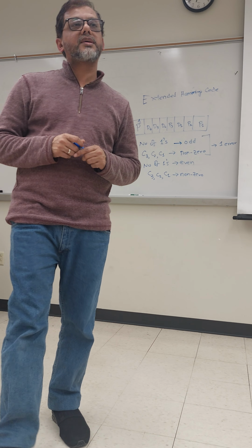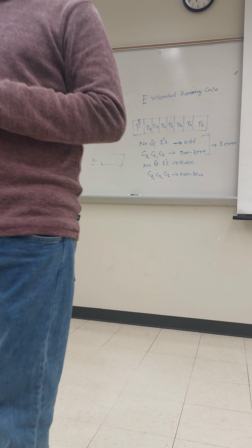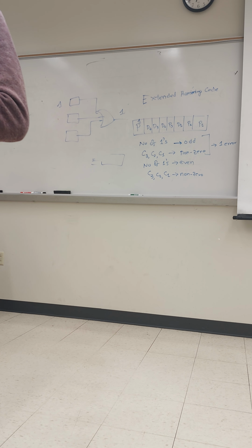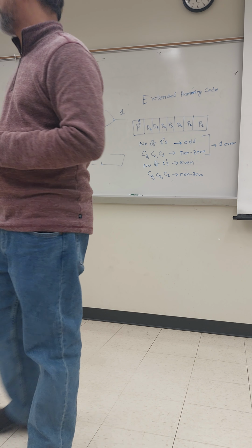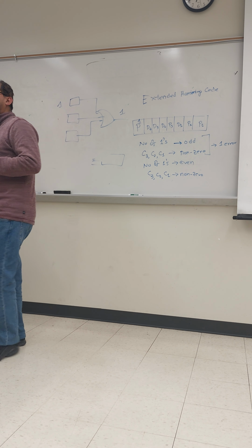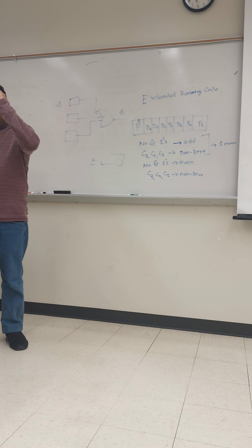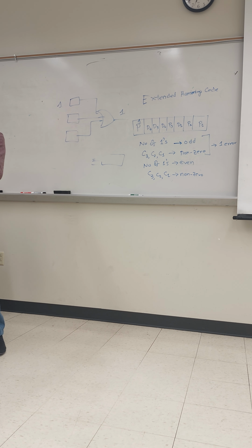And sometimes we can see that in most of the cars, after 30 seconds, the alarm turns off. So if you use a timer circuit for 30 seconds, it will turn off. Nowadays it actually keeps continuing to give the siren, at least 2 or 3 minutes. So this is the use of the AND gate. That means the output will be high when all the inputs are high. So this is the application of the AND gate, a seatbelt alarm system they use.